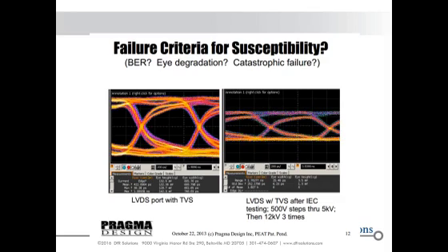such as this differential link here, as the device was struck with about 20 strikes of system level ESD. While it was running, the transmitter output eye diagram started to collapse as the leakage within the device at high frequencies dropped, but it was still not visible damage. So you have to set your failure criteria. What are you trying to call a failure? If I strike it with 8 kV, it may die, but if I strike it with 5 kV 50 times, it may be a walking wounded, as we were mentioning.